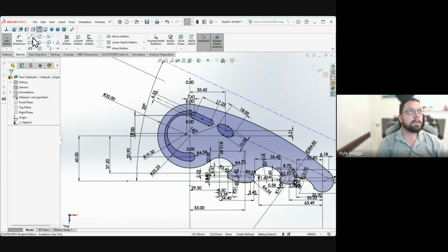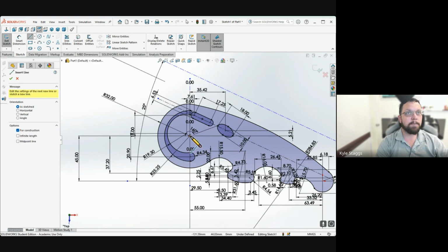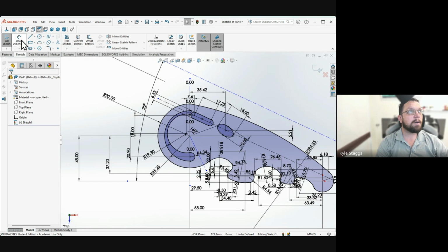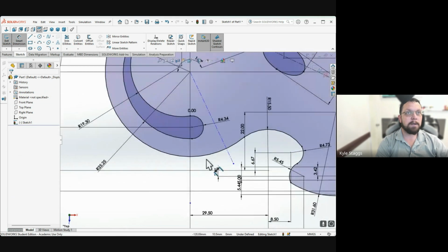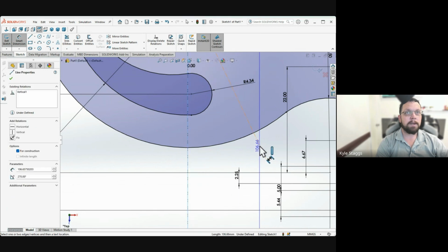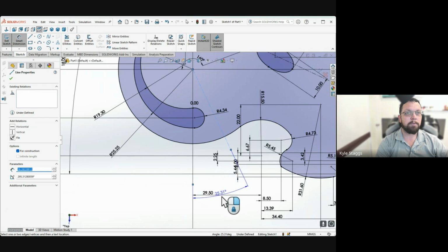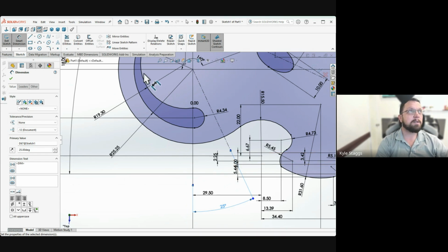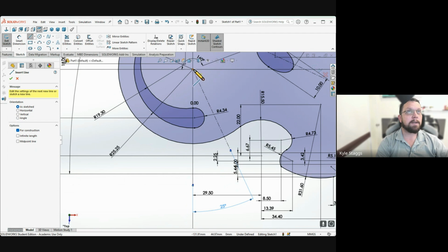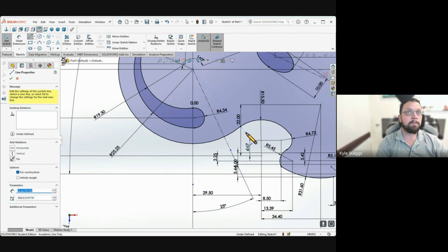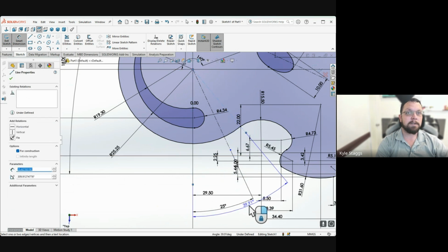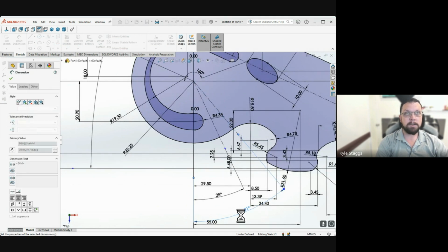You can then do a center line here, and you can specify the angle. So again, clicking somewhere along that line, not like a midpoint to midpoint, because that'll give you a vertical distance. Maybe this angle needs to be 25 degrees. Maybe you need another one at 30 degrees or something like that, where this needs to intersect. And you say, okay, between this line and this line needs to be, maybe it's 40 degrees exactly.